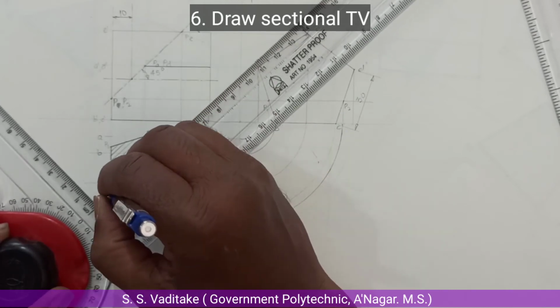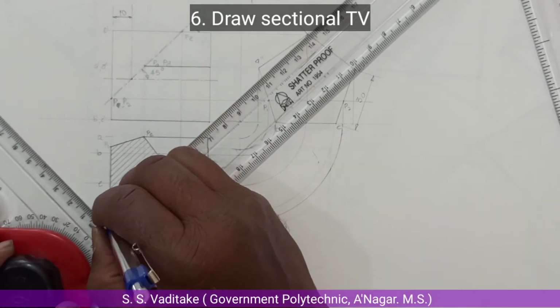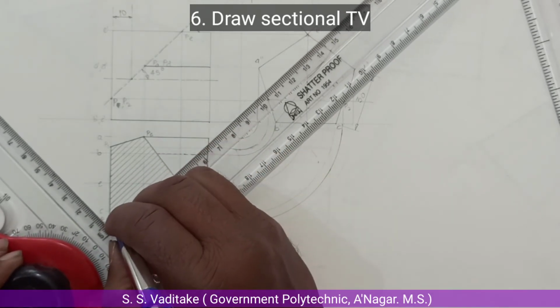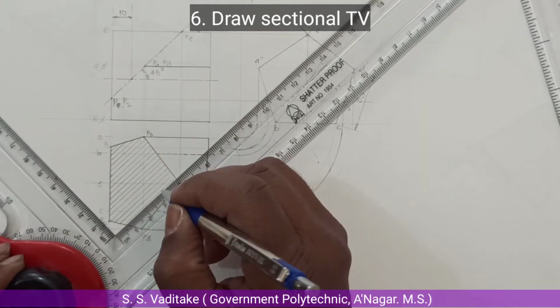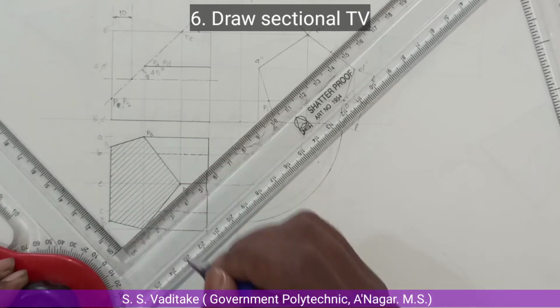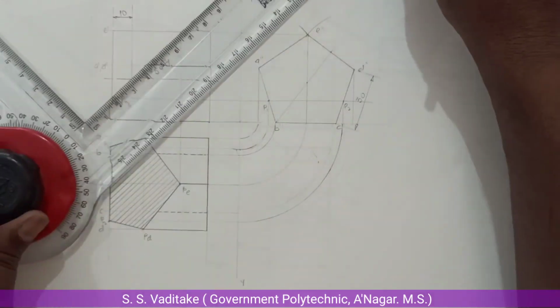Then draw the hatching lines to show the sectional top view. These hatching lines should be equispaced, having a distance of 2 to 3 mm approximately, and all these lines should be parallel and of uniform darkness and thickness.